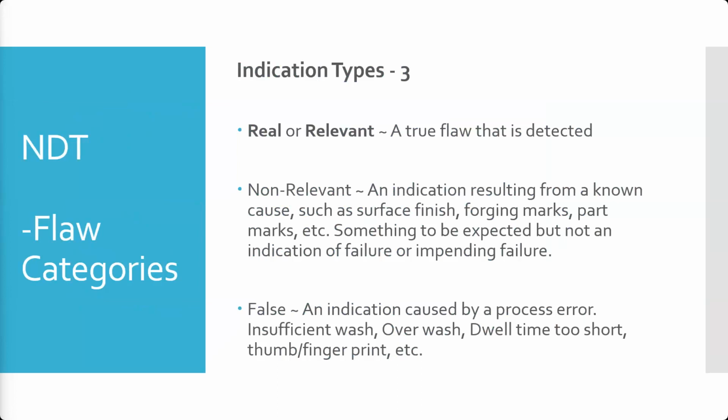Now they're so narrow you can't see them with the naked eye. The other determination is how quickly they were growing. So we would do these dye penetrant inspections. We would actually find cracks more often than not, but most of the time they were little, a quarter inch, a half inch, right? And that was okay.